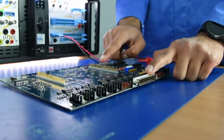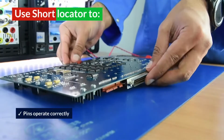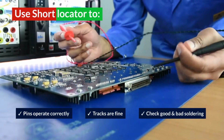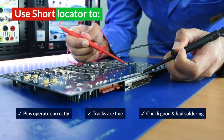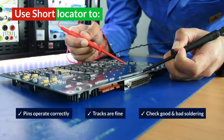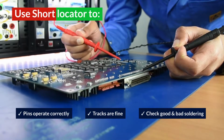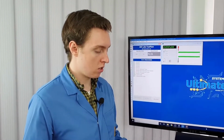Sure, so let's say we have a PCB and this PCB has many different connectors on it. We can use a short locator to see whether these pins are operating as they should be, whether the tracks are fine, or we may find that some of the solder has come apart over time. Then we can go back and reflow this connector, come back with the short locator, measure that these pins are connected as they should be, and then use it in the field. Okay, so you mentioned in the field,